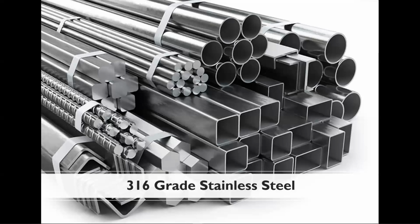And we know typically post-processing can improve a multitude of the issues inherent to this additively manufactured metal, including the surface modification and electropolishing that's been done to help reduce the structural defects and residual stress at the surface.